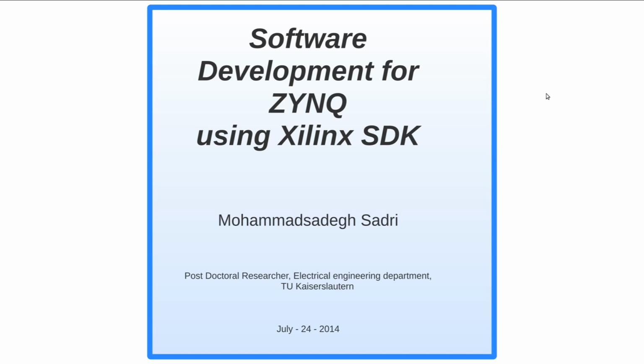So in the two previous sections of lesson 9, I talked about an example hardware that contains a chain of AXI stream components and then the AXI DMA, and we are going to actually program this AXI DMA using the ARM host so that it operates for us and transfers the data from the AXI stream components to the DRAM memory.